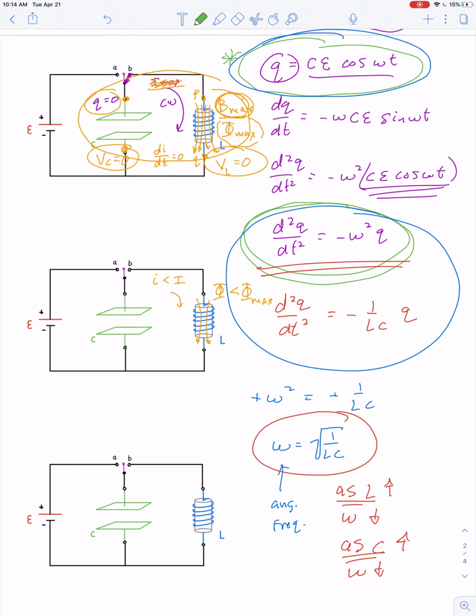So the inductor would like to create an EMF that tries to make the current return to its max value, so that we bring back those magnetic field lines that the inductor has grown accustomed to, so to speak. So now the voltage across the inductor, point Q becomes positive, point P becomes negative, and that would tend to drive greater current in a clockwise direction.